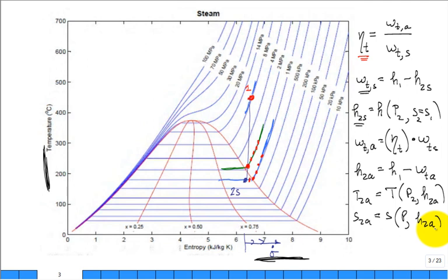And the type of line that is traditionally drawn is a solid line when we have reversible expansion through a device like a turbine, and a dashed line down to state 2 actual, the dash indicating it's not reversible. There are some irreversibilities, and the pathway is not exactly known. We just do a dashed line.